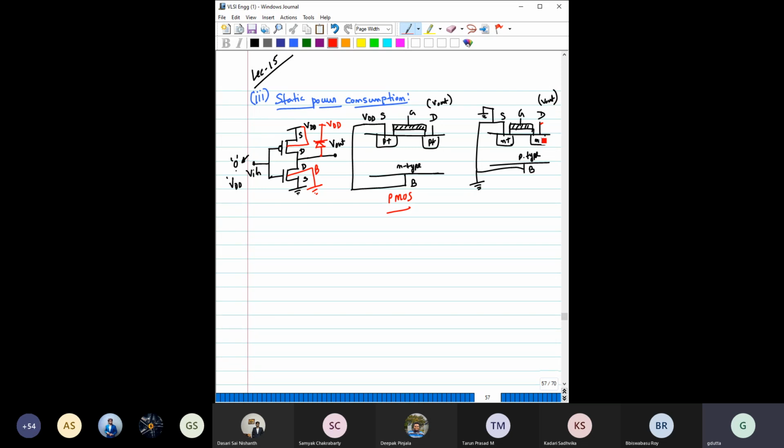Then that also makes this PN junction reverse biased. So we can illustrate this like this, right? I probably have to change the diode direction because here P is connected to ground, so it should be like this. That way we can model this total phenomenon by introducing another diode here, right?